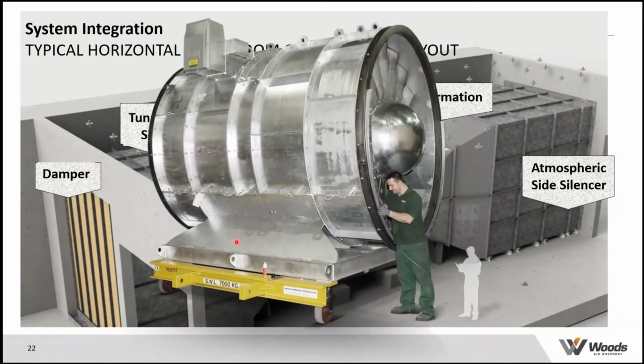And just to give you an idea of the scale, just to prove that this is a real project, this was one of the fans that was built for this project. This is towards the larger end of our range, so this is actually a 2.8 meter diameter fan. It's built in multiple sections to allow it to be disassembled in situ, and I think it had a 500 to maybe 600 kilowatt motor. So it's a very substantial industrial fan that was supplied to this project, and it's 100% reversible, so the fan can be operated equally in either direction.